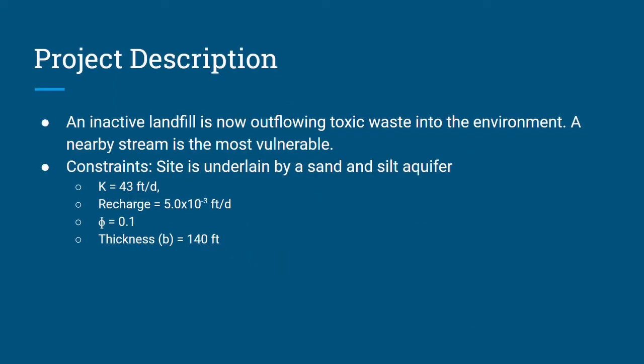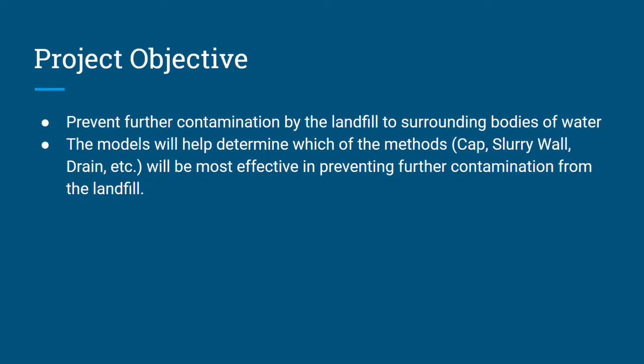In our project, we looked at an inactive landfill which now has outflowing toxic waste into the environment, and there is a body of water that is vulnerable to these toxic wastes. Our constraints include that there is an aquifer made of sand and silt. The hydraulic conductivity is 43 feet per day. There's a recharge of 5 times 10 to the negative third feet per day with a porosity of 0.1, and the thickness of the aquifer is 140 feet.